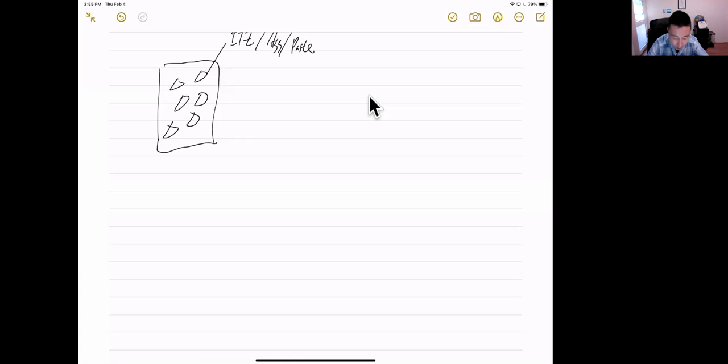For normal concrete, the weakest link will be the ITZ or the paste. So as a result, when a crack is generated, it will start from the ITZ and go through the paste, something like that. And we call that the weakest link theory.